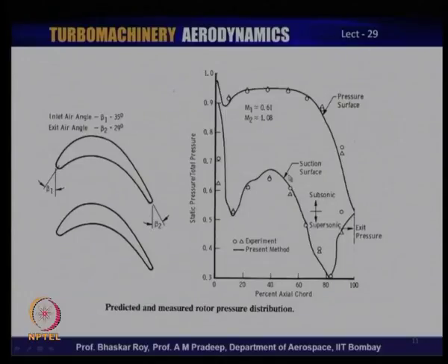So, the acceleration that is taking place would give you the reaction, which will give you the additional work that is accomplished by this particular rotor. And one can see that finally, experiments have been done in a cascade tunnel to match the experimental values with the design values, so that you are assured that you have a reasonable match between what you have designed and what you are likely to accomplish in actual blades.